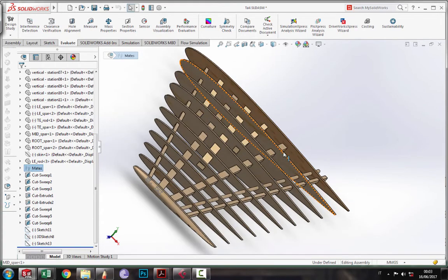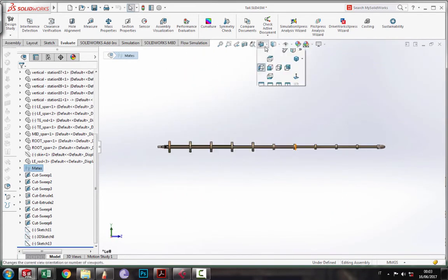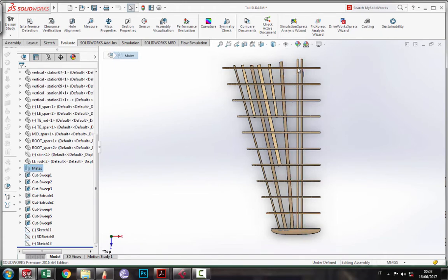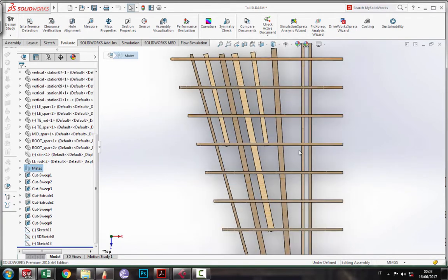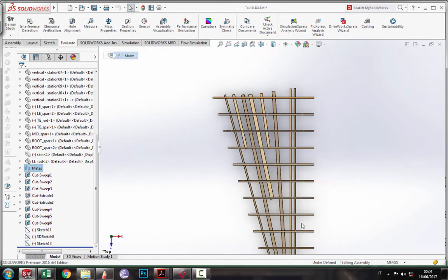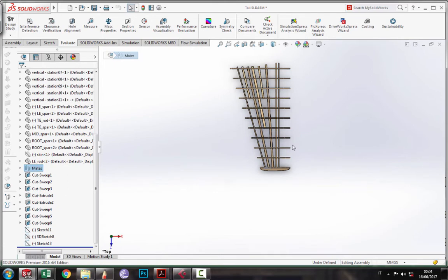Okay, so once you have this, every hole you see here is by myself. There is no rule. I will just show you to know. I did one which is 9 degrees, and then the other one is a random angle. The story is that near the root we need to have very stiff integrity, with a very stiff structure, and at the end we need just a little bit, not because the tip is strong, but just for weight. This is the famous cantilever configuration.